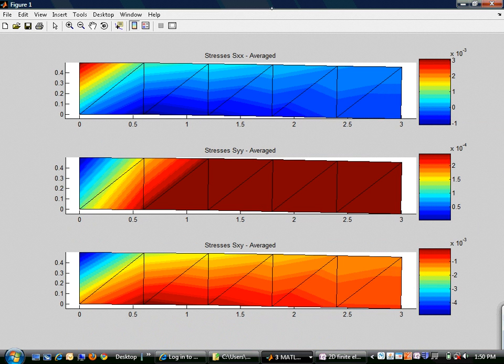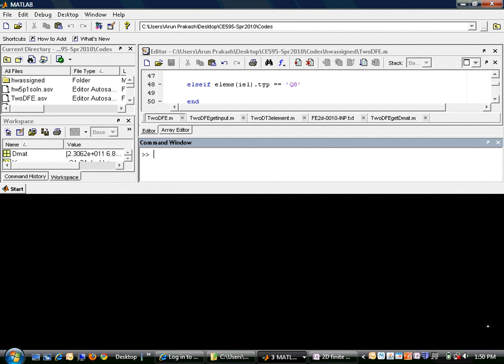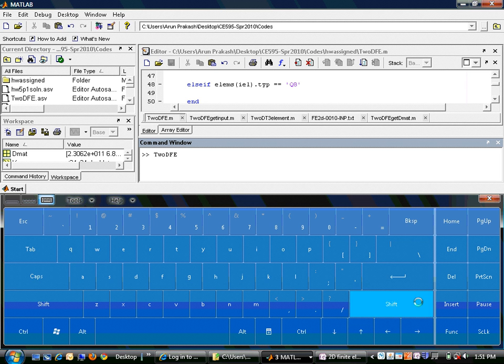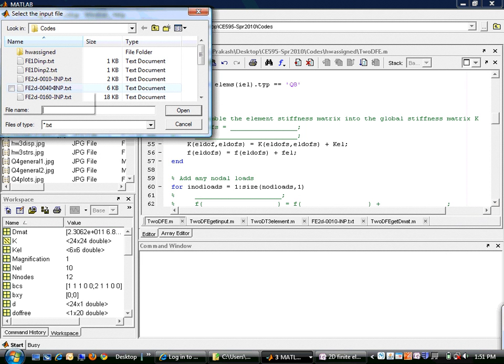But still, you can see that the displacement that you get at the tip is barely 0.05 or something. And both these nodes are constrained in the X and the Y, so that is also not a good boundary condition to use. So if you use the next finer mesh, what happens? The next mesh has 40 elements.